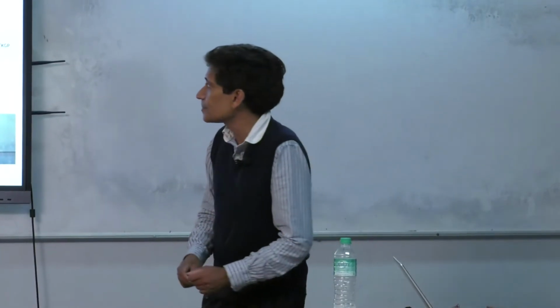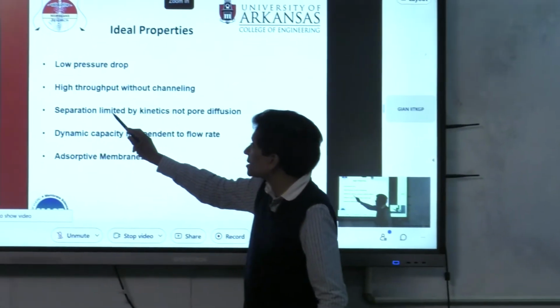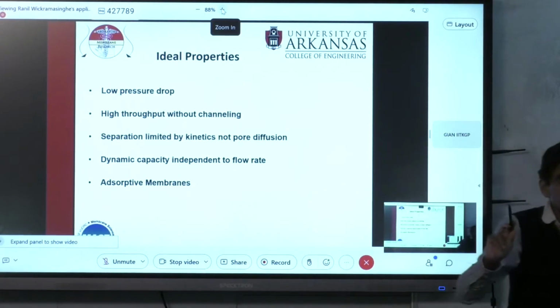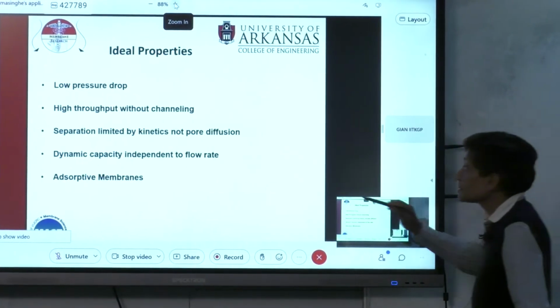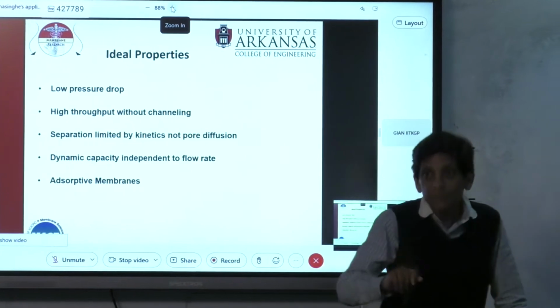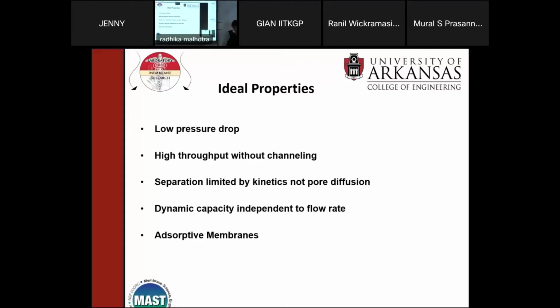You're wasting them, okay? So we'd like the separation, this is in terms of mass transfer, to be limited by the kinetics of adsorption and not pore diffusion. So if you study this, you have various mass transfer resistances, and we want the kinetics of adsorption to be limiting. Dynamic capacity, we'd like that to be independent of flow rate, and so that's where the attraction of these adsorptive membranes, or pure membrane chromatography, comes in.